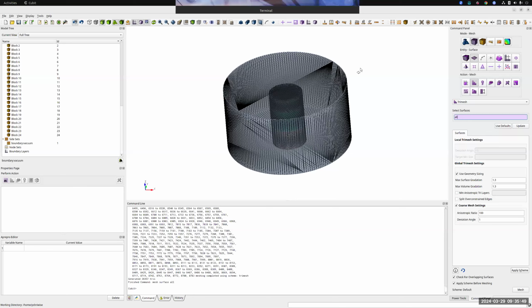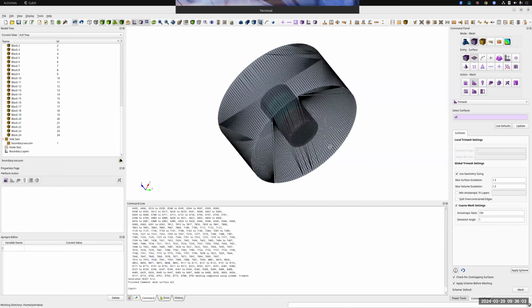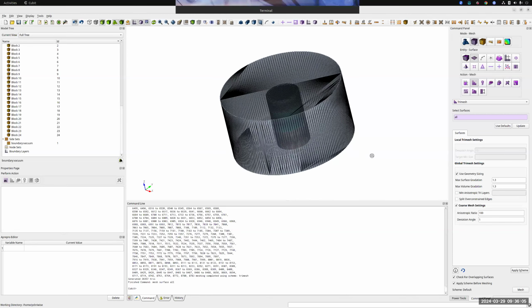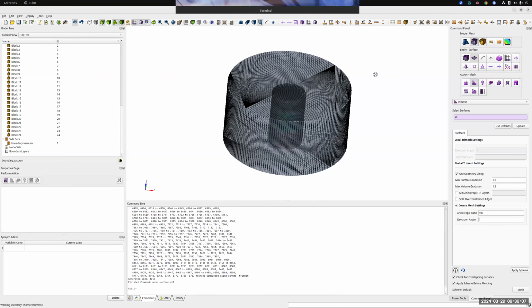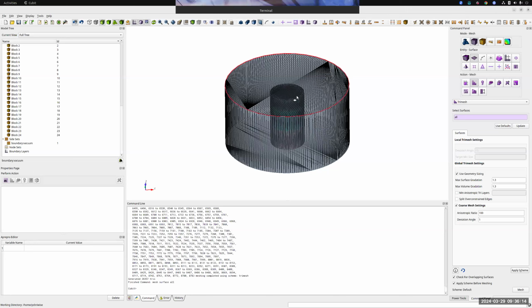In old DAGMC export workflows, we would export this, and it would result in our H5M file or mesh file. But then we have no way really to understand what that mesh looks like, or whether it's covering our components well, or just generally whether it is well formed. Whereas here we can see it up here on screen right away, which is good. And again, this mesh is made watertight inherently as a result of coming from this trimeshing algorithm.